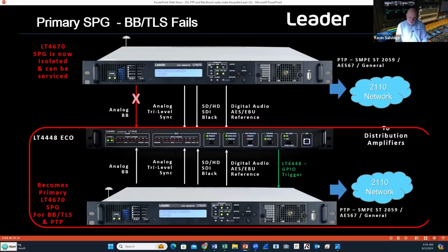So basically, you've used the emergency changeover unit to trigger the best master clock algorithm to change them, because you've changed the preset, you've changed the priority, and you've raised the level of the backup SPG, so it becomes the Grand Master. Yep.